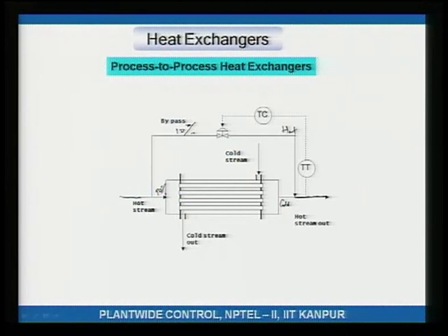So here the temperature control, because of this bypass, would be extremely fast. If you change the valve position of the bypass valve, the temperature would immediately respond. So the open loop dynamics is fast, therefore the tuning or the closed loop response or the tightness of the temperature control would also be pretty good. That is because temperature responds immediately to a change in the fraction that is bypassed, right.